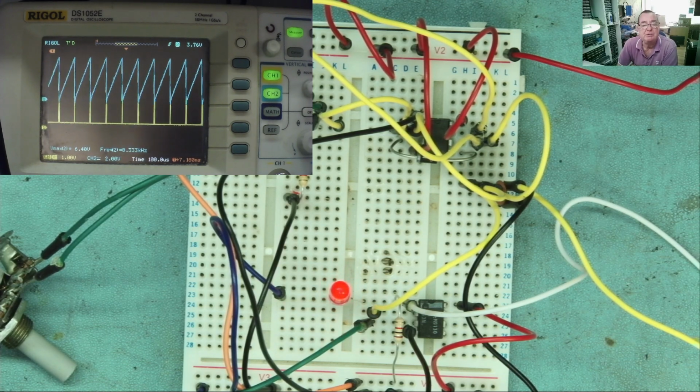I did say originally, the title from this video, all you need to know about PWM to fix stuff. So what generally goes wrong with pulse width modulation? Well, normally speaking, what goes wrong is not the pulse width modulator, but the circuit, or rather device it is driving. So the output MOSFETs, the transistors, whatever is handling the high power, that's what tends to fail.